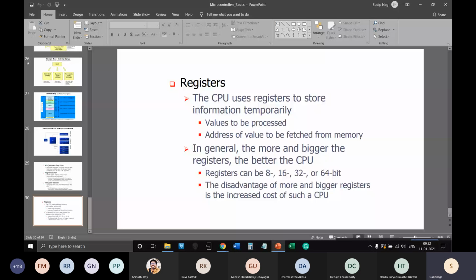If you have forgotten what noise margin is, I'll quickly tell you. Noise margin is the range of voltages that could be considered as logic 0 and the range of voltages that could be considered as logic 1, at either input and output, and the difference between them. There are definitions and equations for noise margin. You can look at it. There are 4 equations in noise margin.